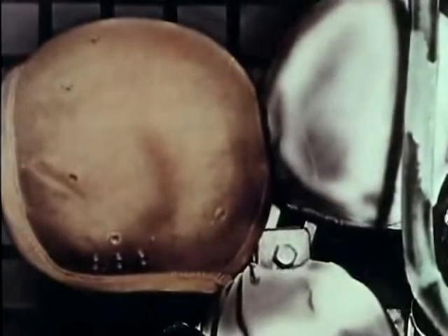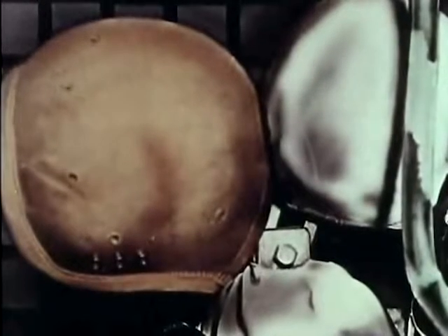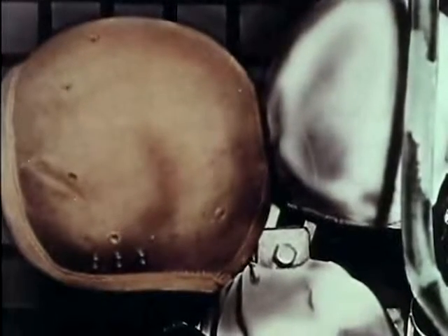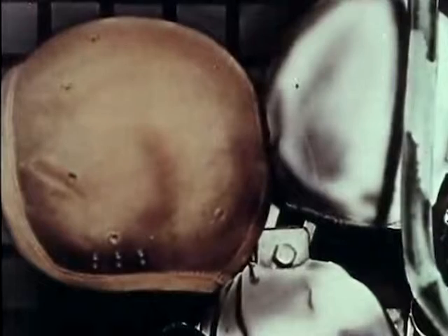Again, watch the dummy in the rear seat. Unfortunately, the fuel mist obscured the actual impact of the dummy's head with the front dummy. However, a post-crash inspection revealed a dent in the dummy's helmet. Here is the position of the dummy's head when it struck the front dummy. It has been shown that some of the benefits of a shoulder harness are lost if the harness stretches excessively in the crash.